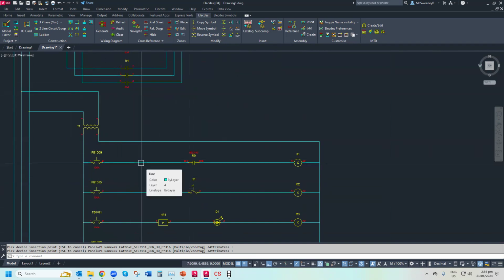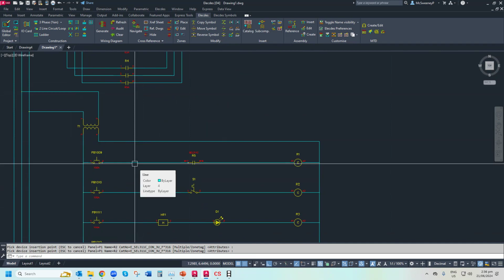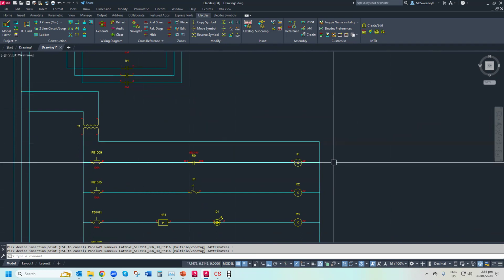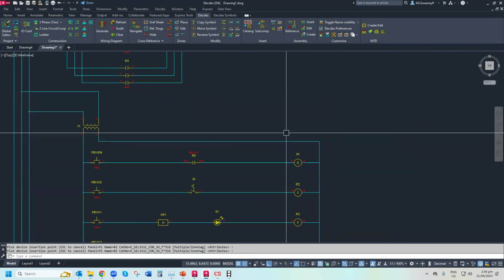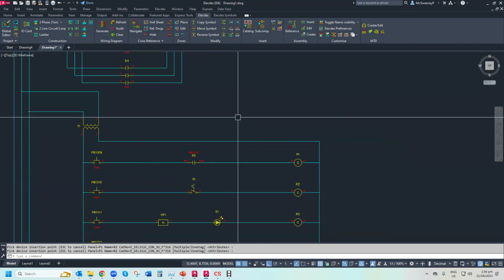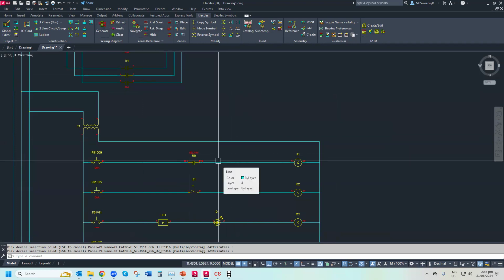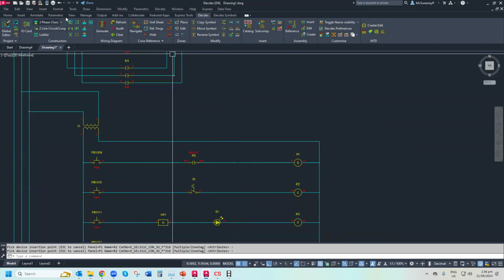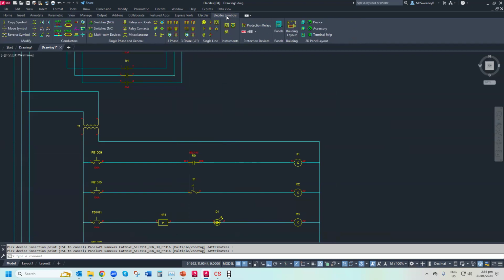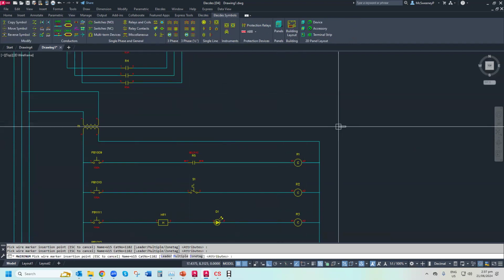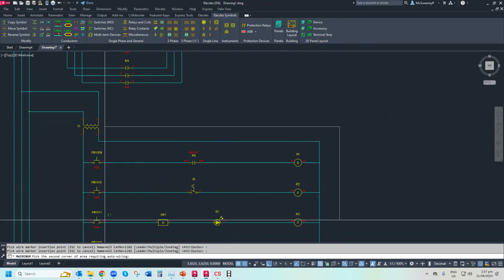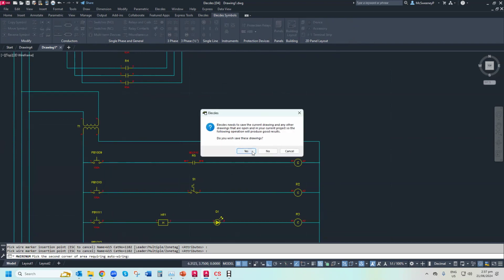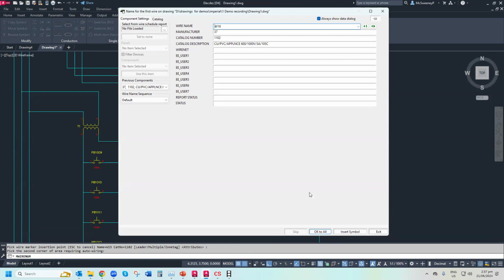And this is why we can produce wiring diagrams. We treat a line segment as a conductor, i.e. a wire or a cable, and a polyline, if you want to have an arrow saying service this in 2025, make it a polyline. And if you have conductors with no conductor names, it will let you know that at the end, which is one of the errors I showed, which is why I don't put in all my wire numbers. I just do a little crossing on some, and you can see it's assigned discrete wire numbers.